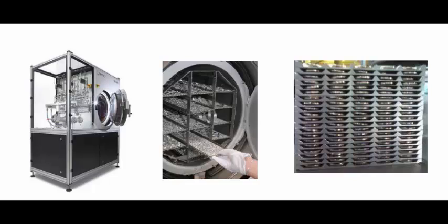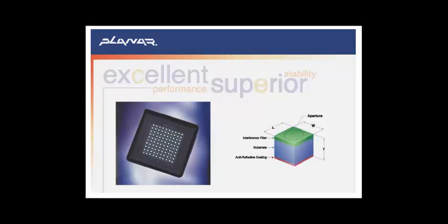When we come to optics, high uniformity and accurate thickness control make ALD attractive for optics. Recently, Planar company developed a multiple cavity Fabry-Perot filter for their WDM applications, and the device consists of about 200 layers and still has a thickness of just 45 microns.